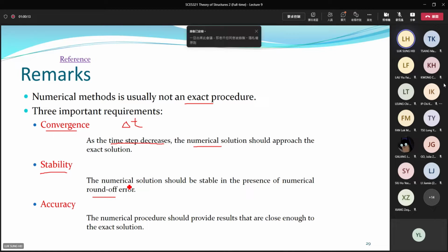Some guy proved that there are some suggested limits on how accurate a result can be achieved if you want to set a time step, as shown on the next slide. Accuracy is the difference between your answer from the numerical scheme and the exact solution. For some loading, like sine loading, you know the exact solution. So you can use this kind of well-defined loading to check the accuracy of your method, Newmark's method or central difference method, etc.